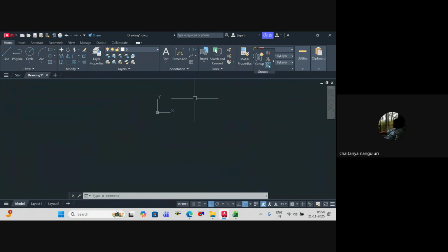See, if the smoke is transparent, it is not black or opaque. So when it is transparent fumes, will optical type detectors work? No, sir. Obviously not, because for optical to work, the smoke should basically reflect the radiation or stop the radiation. Right? So it should be opaque. For that reason we don't use the optical type. In special applications, you have to use something called the ionization type.